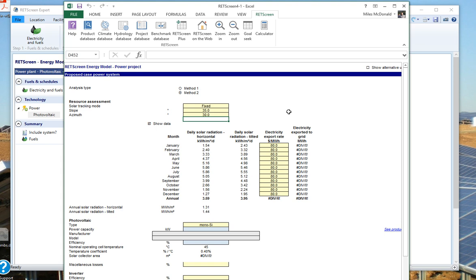If I point it a little more towards the west, this number drops down, but we're not actually going to be getting the full use of the morning anyways. So you need to point it so you more fully collect what's in the afternoon. What I'm trying to point out here is that shading matters. Dirt matters. Other localized influences matter when it comes to sizing and pointing your array.